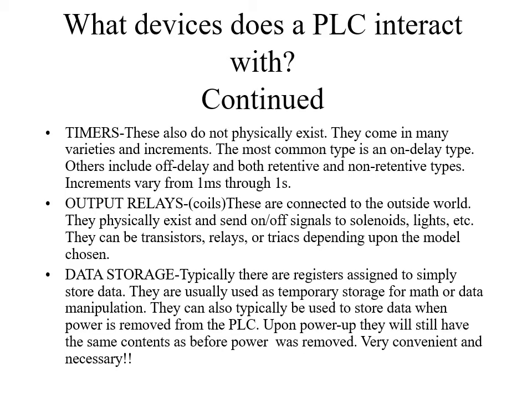Next, we have output relays. These are connected to the outside world. They physically exist and send on-off signals to solenoids, lights, and other output devices. They can be transistors, relays, or triacs, depending upon the model chosen.